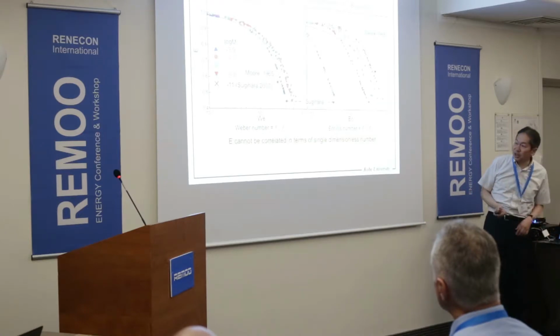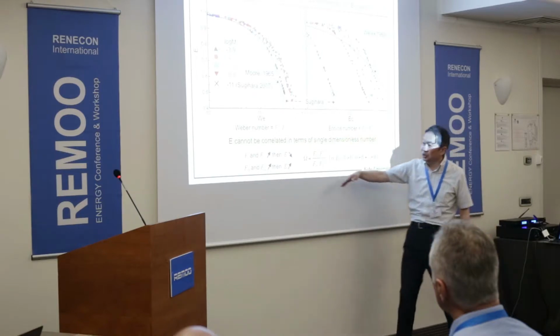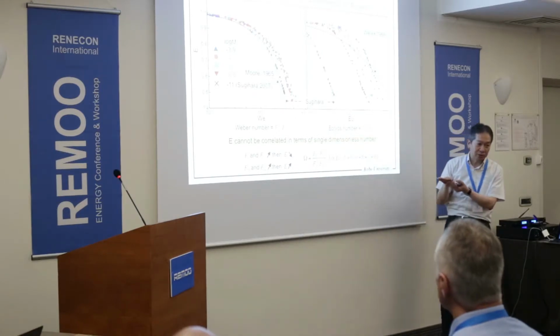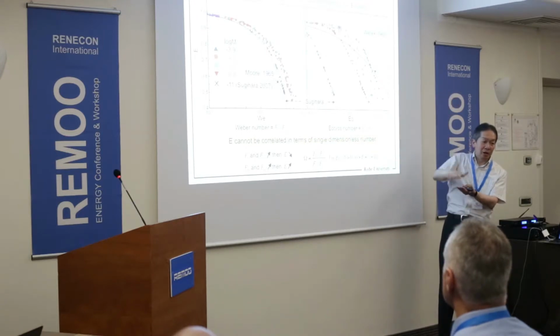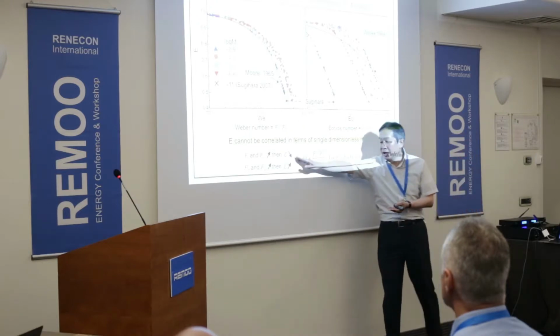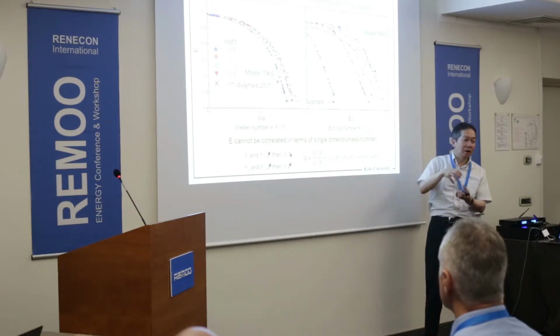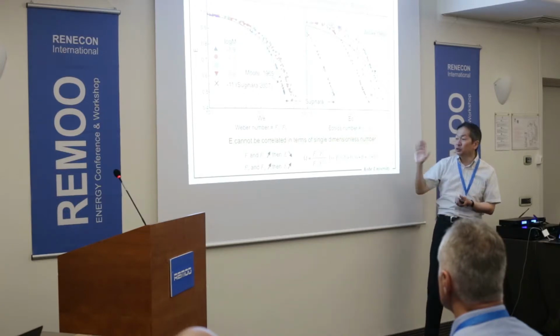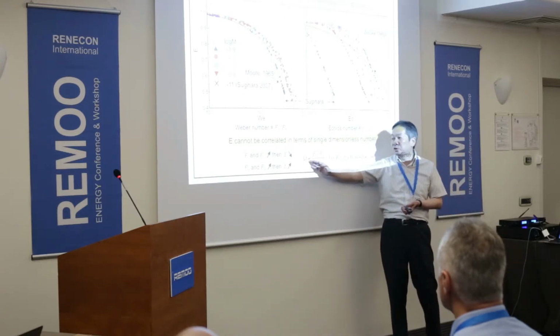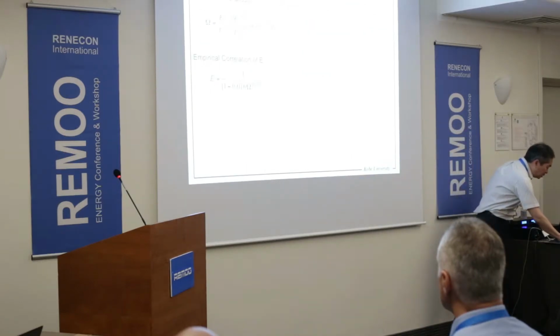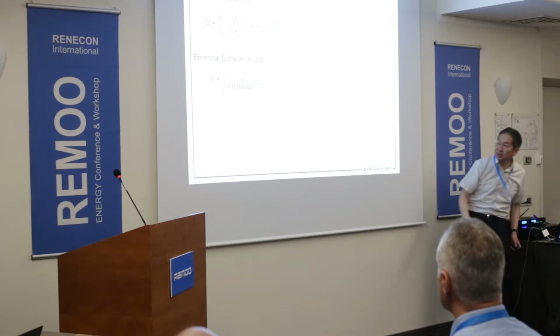So in this case, if the inertia and the buoyancy increase, then the aspect ratio should decrease, because the dynamic pressure acting on the bubble becomes large. And if the surface tension and the viscous force become large, then the aspect ratio should increase. So we should use this kind of dimensionless groups, and using this combination, we propose this very simple